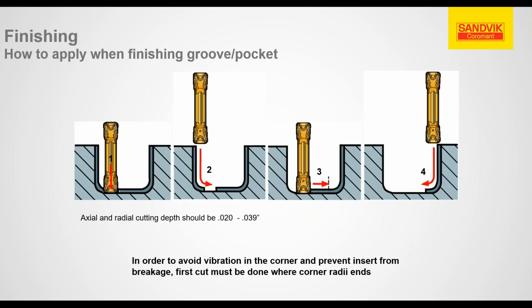And then when you actually finish the groove, it's good practice to actually create a little bit of clearance down at the bottom. Again, this gives the insert room to flex and give some clearance so that you're not binding it and possibly chipping out the corners of the insert. And this should give you the best finish possible and reduce any risk of vibration.